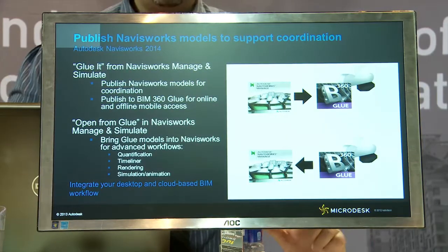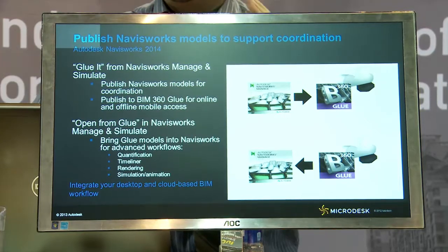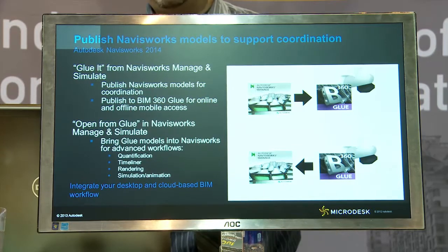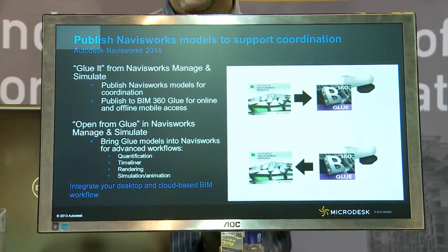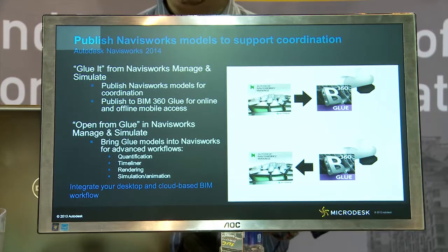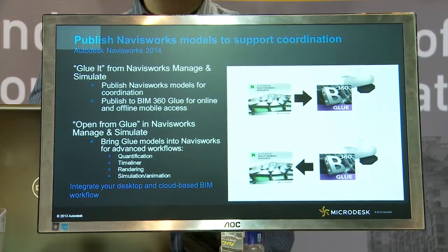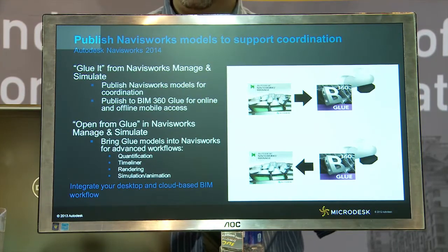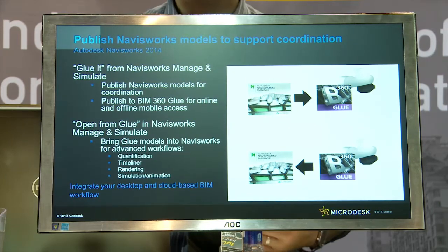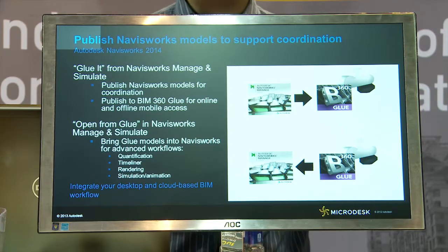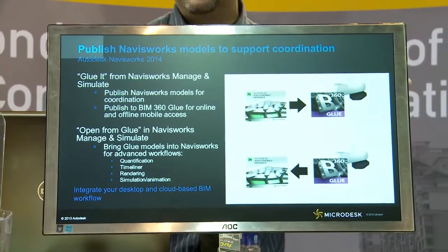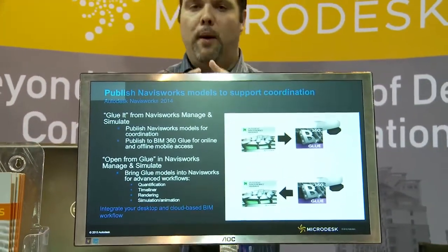One last thing is the ability to integrate it, and this is a new 2014 feature, integrated with Navisworks. That means that now, from within Navisworks, you can go straight to Glue and back from Glue and start working on the same model. Why is that a good thing? Because Glue has its limitations in terms of what you can do. You can generate the clash reports, access all this information, and navigate the information, but in terms of generating, let's say, the 4D analysis for sequencing the project construction or mapping the project schedule, that's something you go back to Navisworks for. It's the seamless integration that makes it great, because they both complement each other.